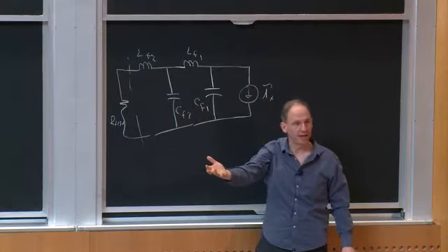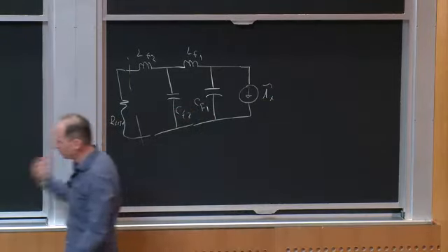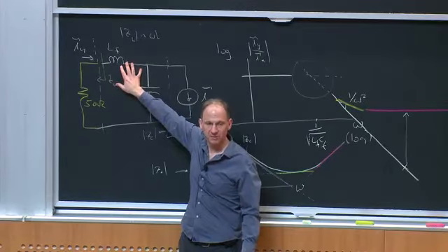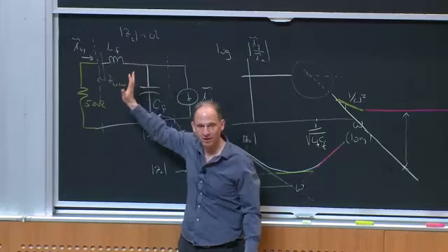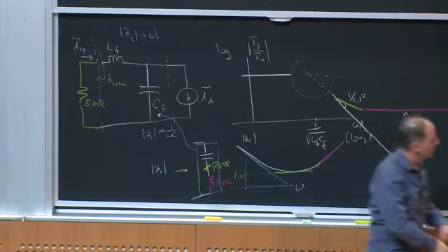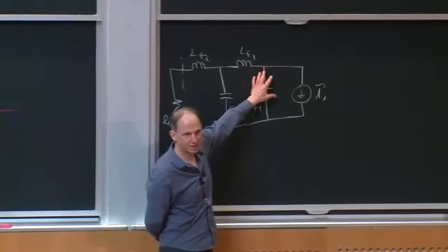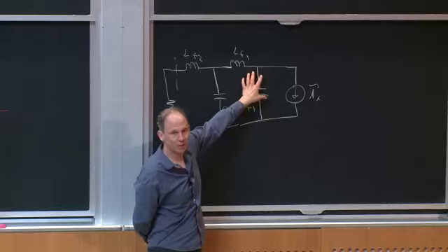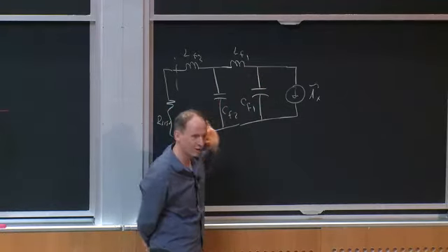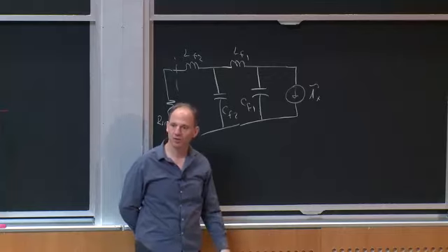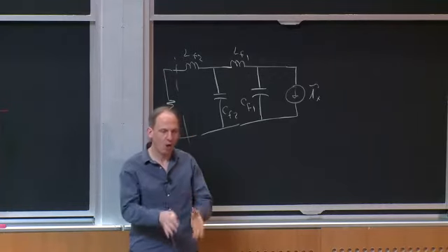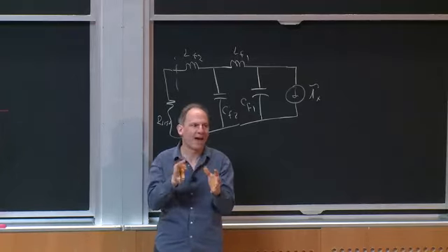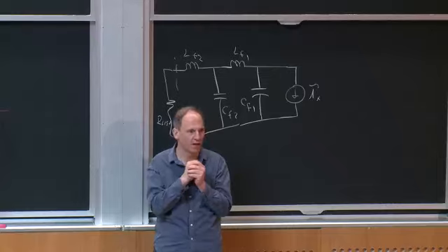And it may be better to do that even in a lot of cases, because even putting aside the parasitics, I can move the cutoff frequency down, 1 over the square root of LC, right? By using bigger and bigger components, I can move that cutoff down. Here, maybe I use smaller components, but instead of getting a 40 dB per decade roll-off, I could theoretically get 80 out of this. So even if the net cutoff's higher, that fast attenuation will help me. So it's often better to go for smaller multi-stage filters than one big fat single filter stage trying to get the attenuation I want.